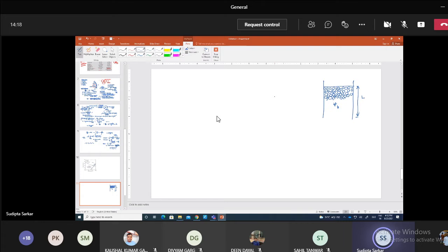Okay. Now, if we try to find out the flows, normally for pipe flow, the head loss formula is given by 2 f L v square by 2 g D, where, what is this D? D is not like the diameter, it's probably the hydraulic mean radius. So if you write hydraulic mean radius, for a pipe flow, this is pi d square by 4, which is the area, divided by P, which is pi d. So this is wetted perimeter.